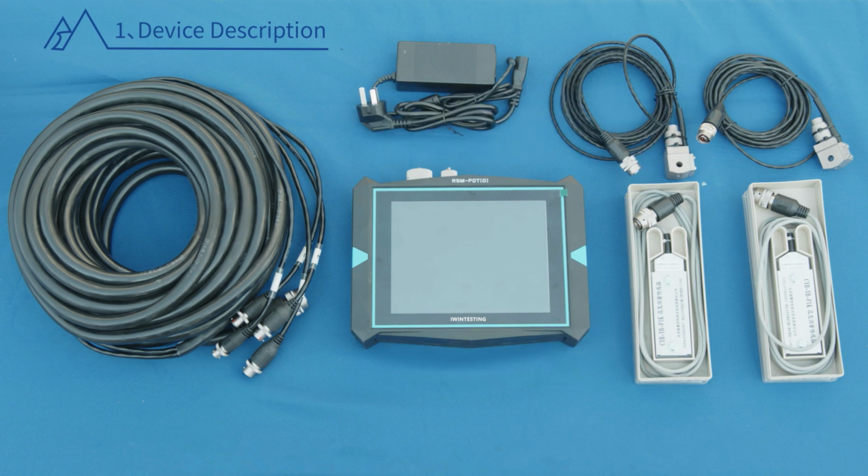The high-strain pile bearing test is a type of dynamic testing method to induce the resistance of the surrounding soil and the supporting force of the pile end in case of sufficient relative pile-soil displacement when the impact pulse is spreading downwards after the pile top is impacted with a hammer.